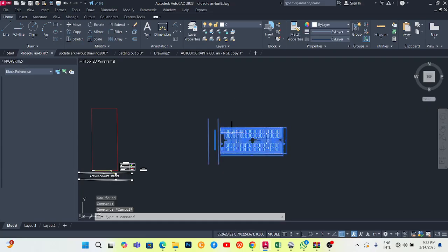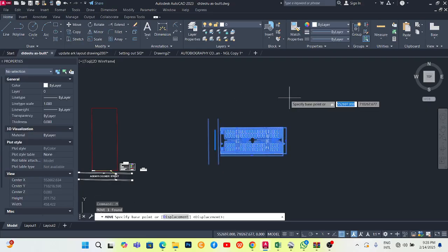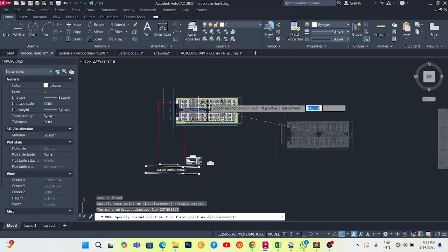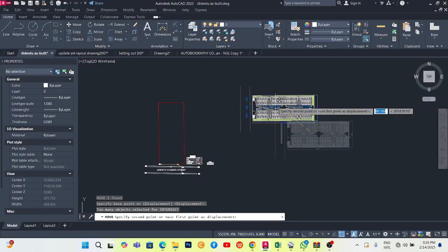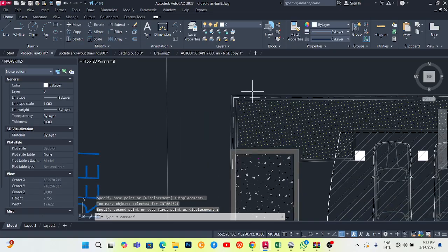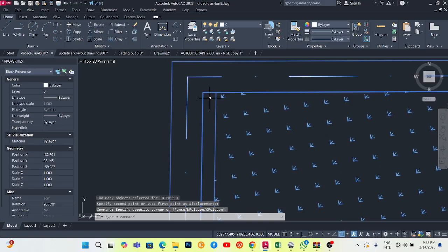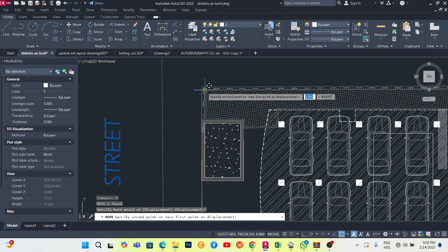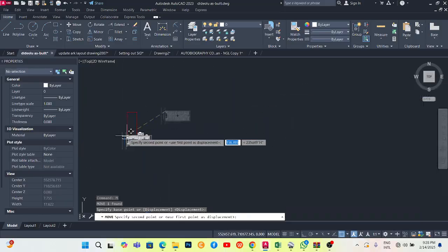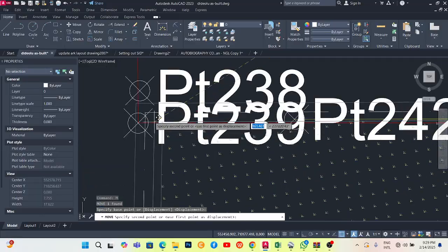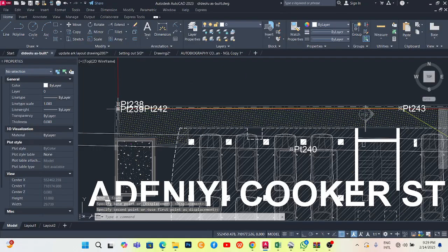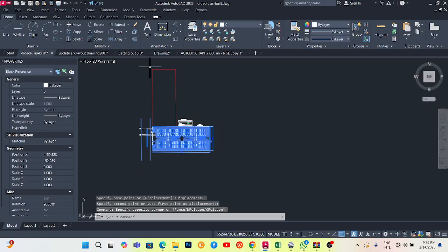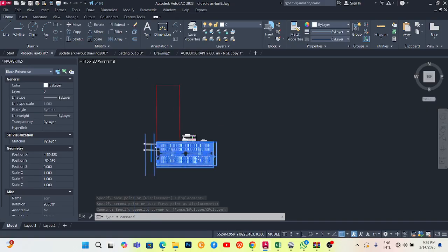So I will now move it to my as-built, because the as-built is georeferenced, so I would not like to move it away from where it is. I will just be moving the other drawings into it. Let me use this edge as reference line. From that edge, I will copy it to this edge because I want to use this as reference line. I'll move it here. Then I will orient it. I want to use this right angle as the orientation.